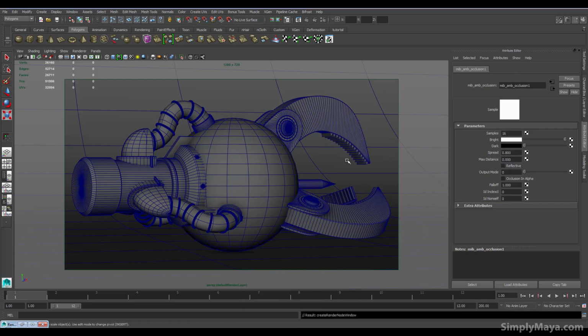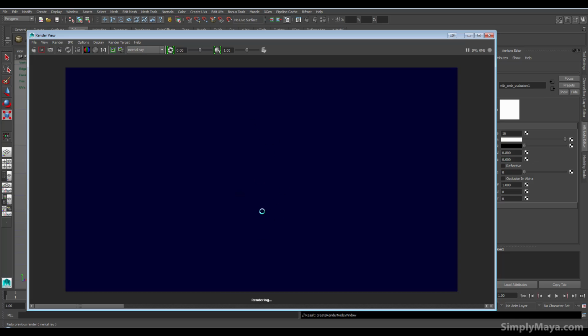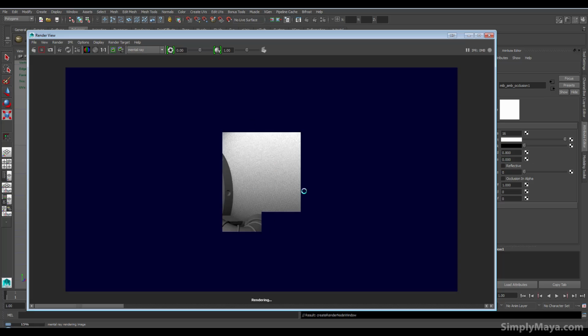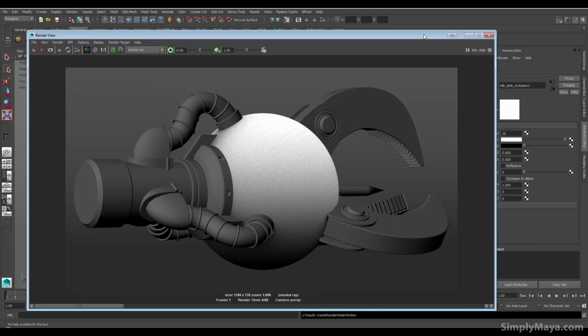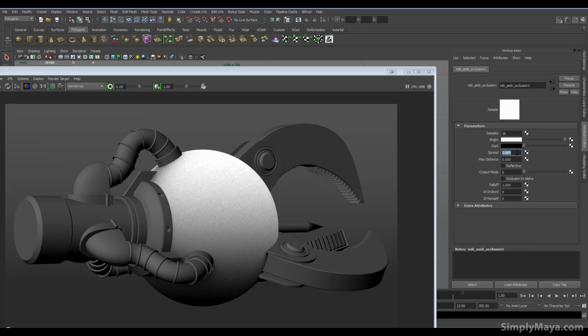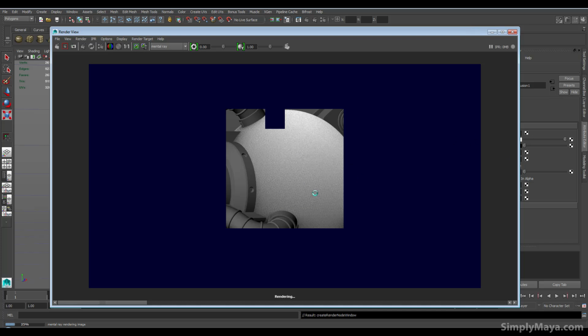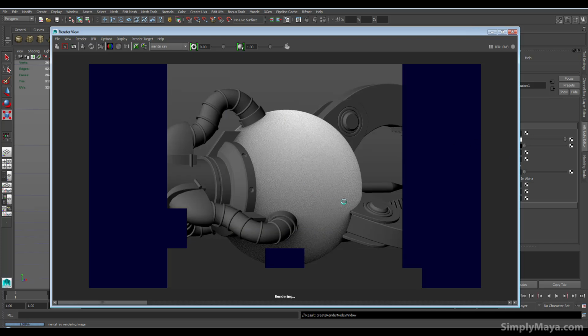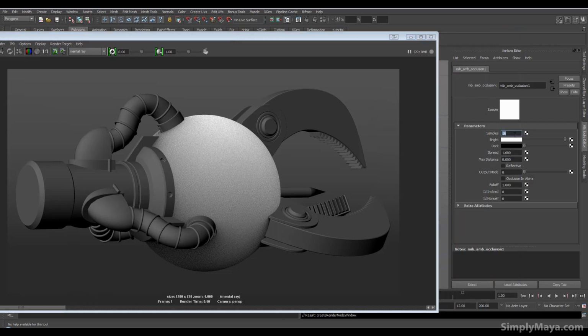This will bring up an ambient occlusion node, and if I render now, you'll see that this sphere looks a bit better, although it will be terribly grainy. So that gets the occlusion on it. Now I'm going to increase the spread of the occlusion. I'll probably double it, and that will help me get a smoother transition. I'm going to leave you to play around with these occlusion options. There's not that many of them, and most of them are fairly self-explanatory. So now I've got more spread on that occlusion, I can come in and increase the samples.